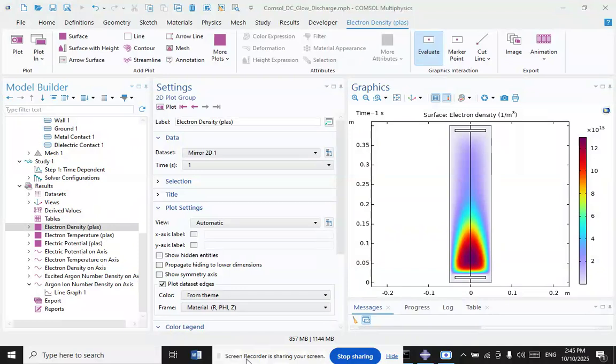A to D region is dark discharge. Ionization happens. Current below 10 microamps. F to H region is glow discharge. The plasma emits a faint glow. I to K region is arc discharge. Large amounts of radiation are produced. Conduction in a gas requires charge carriers, which can be either electrons or ions. Charge carriers come from ionizing some of the gas molecules. In terms of current flow, glow discharge falls between dark discharge and arc discharge.